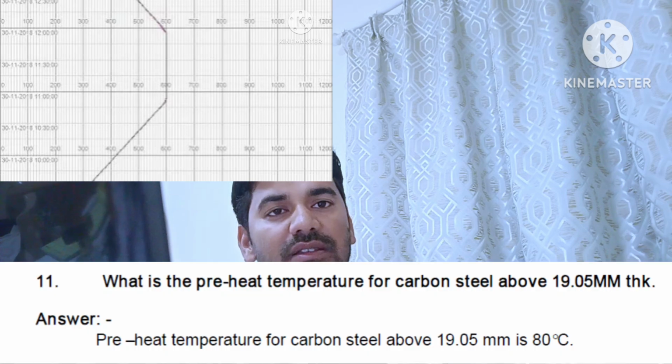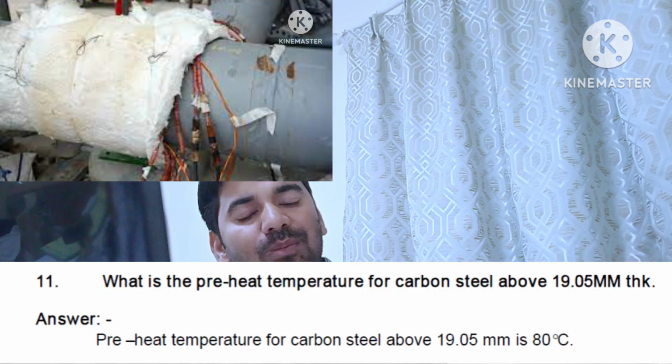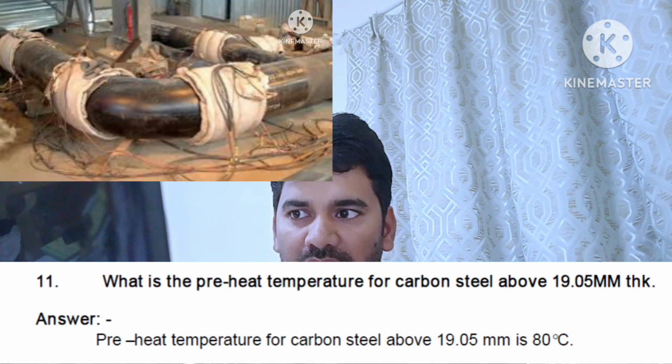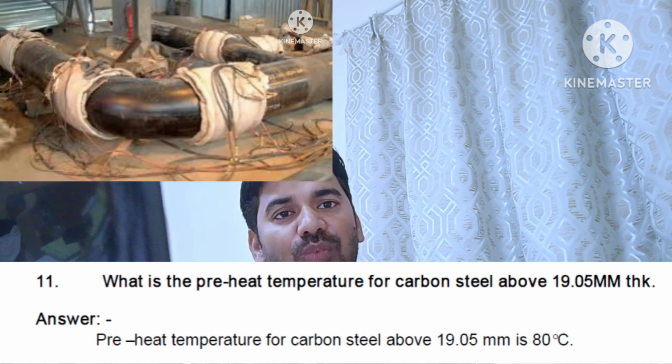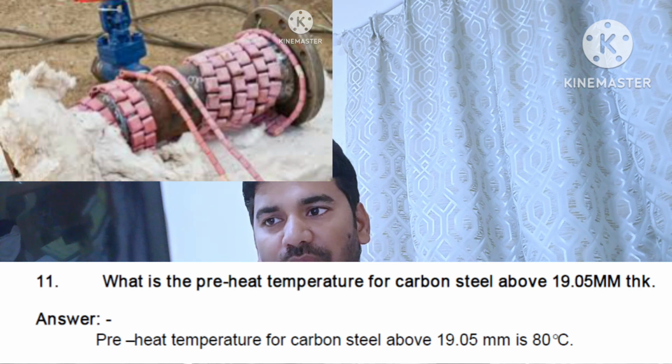What is the preheating temperature of carbon steel pipe if the pipe is more than 19.5 mm thick? Below 19.5 mm thickness, carbon steel pipe needs no preheating.